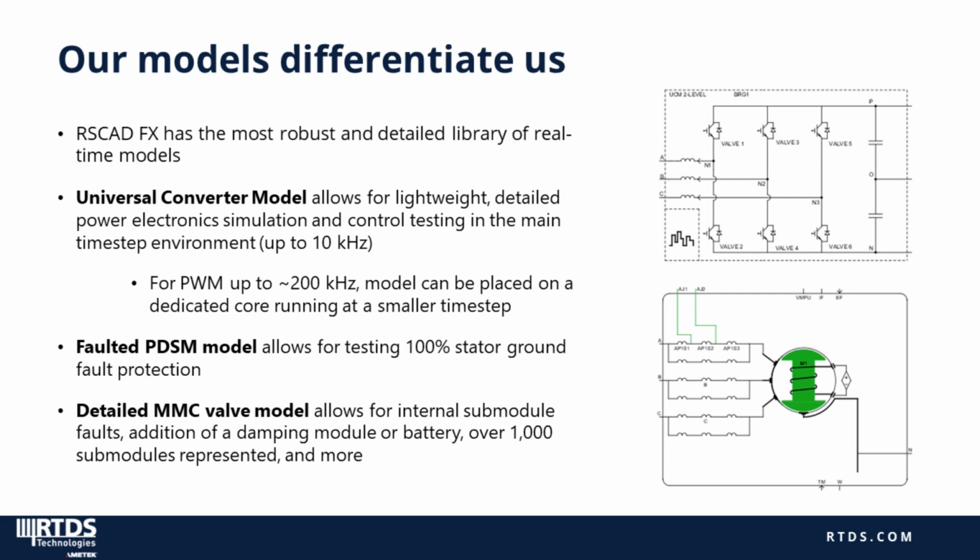And for lower frequencies, it can be placed in our main time step environment, which is really interesting for users with smaller simulator configurations. We also have a faulted phase domain synchronous machine model that can be used for 100% stator to ground fault testing, and some of the most detailed modular multi-level converter models on the market. I won't get into detail on those today, but if you have any questions, please feel free to ask.